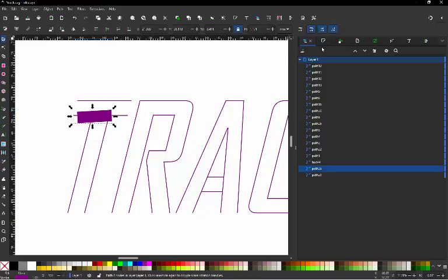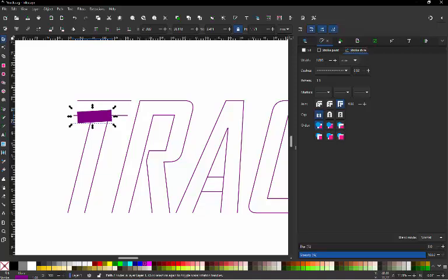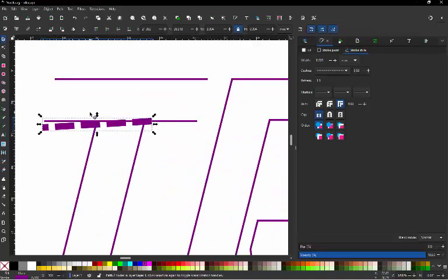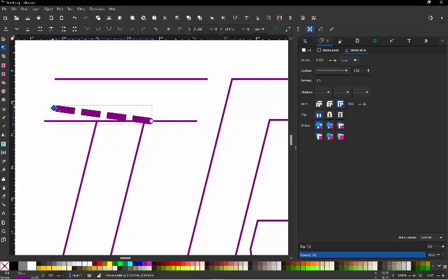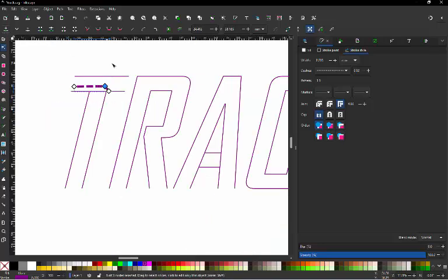So we'll come over here, and I do this every time we add this running stitch. So 0.2, so I can see the actual stitch better. And then, so it's ending here, but we're going to start it over here. And that will give us our connection that we need. Okay.